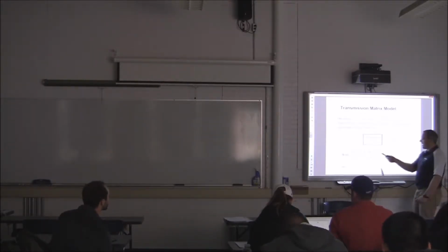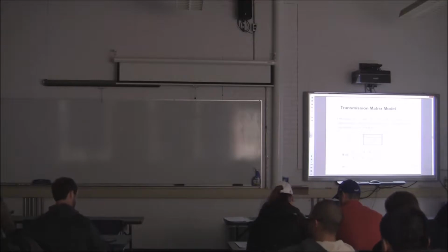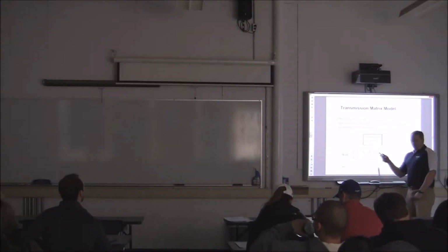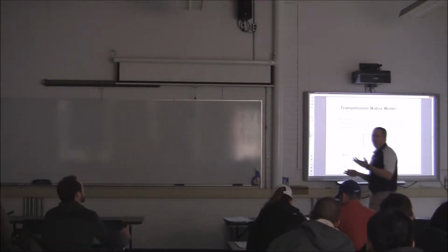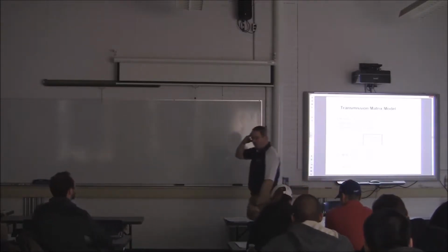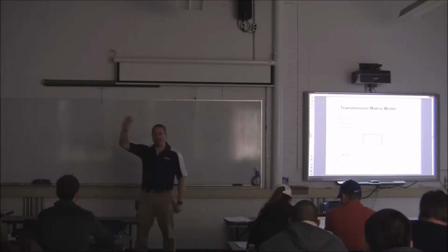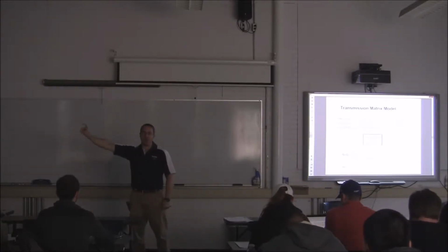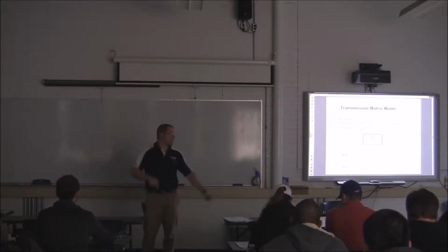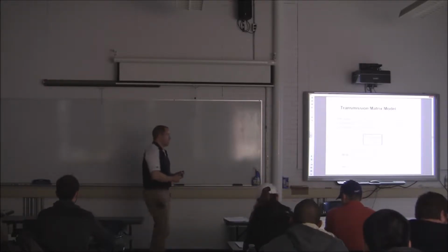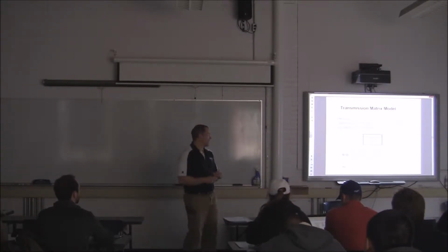So this is all based on the fact that our customers are paying us for a reasonable voltage, right? Plus or minus 3%. So we want to control the receiving end, and then we'll figure out what the sending end needs to be. So that's a little bit of a flip. Typically when we think about power systems or real-world electrical circuits, we always have an independent power source that drives the result of the circuit. This is the other way around. We know the voltage at the end of the line. We need to figure out what the source voltage needs to be to support that voltage. So it flips your thinking around a little bit. Hopefully it doesn't intimidate you too much. It's just a slightly different perspective of things.